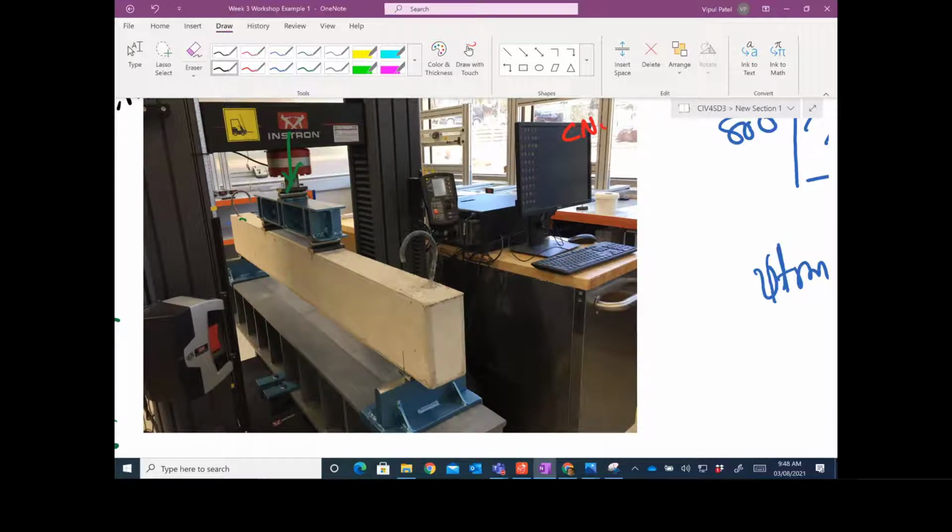Here we know this is alpha 2 f'c. This is the stress in the concrete here. Now we have this area. Let's say this is the neutral axis somewhere here. We don't know that, dn, that we are trying to calculate. And for that one we have this block, right? Because you remember that alpha 2 f'c, and this is your gamma dn, right?